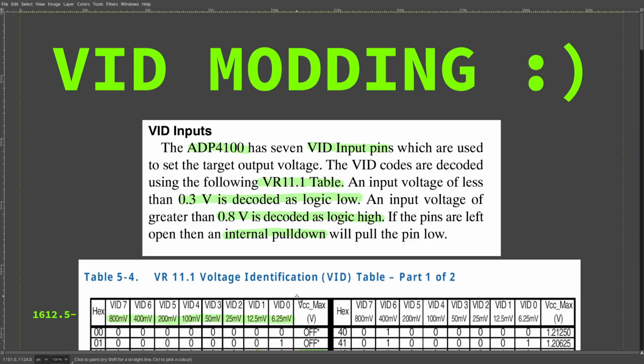Voltage dividers are great for simplicity, but they're really bad for being able to dynamically change the voltage while it's running, or just to change it in general, because you suddenly need to be able to basically change your voltage divider, which messes with the compensation loop, and it gets very complicated very quickly.